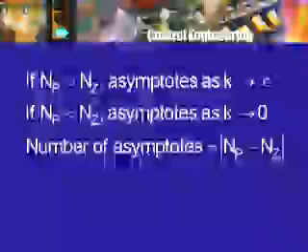In the other case, when np is less than nz, it is going to be just the opposite. The number of branches of the root locus is the larger of the two, that is the degree of the characteristic polynomial. Therefore there will be nz branches, there are nz zeros, so nz branches will end at the nz zeros, but there are only np poles. So np branches will start at poles, and the remaining, the difference between the two, will start from a region which we refer to as the region at infinity. That means for small values of k, there will be roots which are very large in absolute value. That is what we mean by saying that the roots or the branches start from infinity.